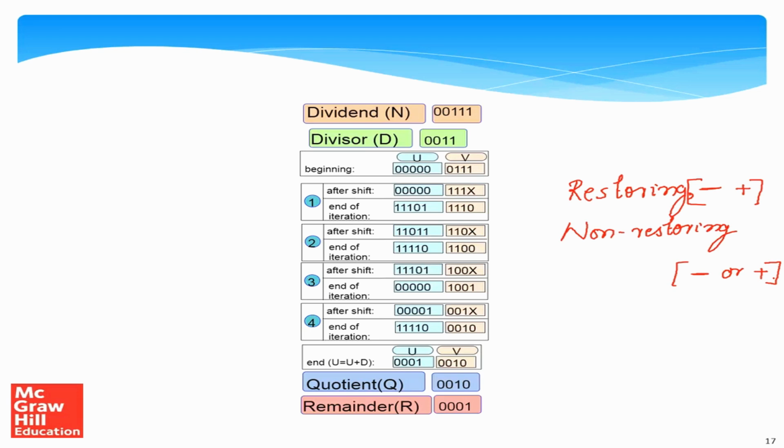And the way that you prove it works is that you start, so the first state is the same. After that, what we need to prove is that every quotient bit is computed correctly. And whenever a quotient bit is computed to be 1, the state of both the algorithms is the same, the values of all the registers are the same. Let's say that we compute the quotient bit to be 1. After this, as long as the bits are being computed as 0, the algorithms will take 2 separate paths.